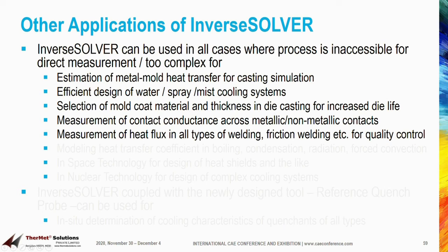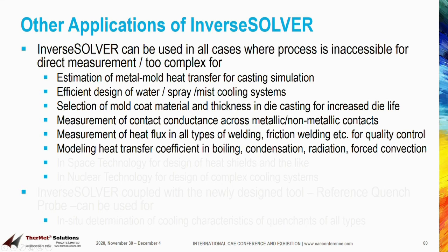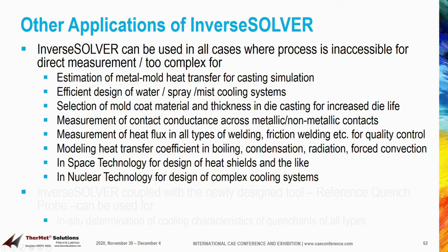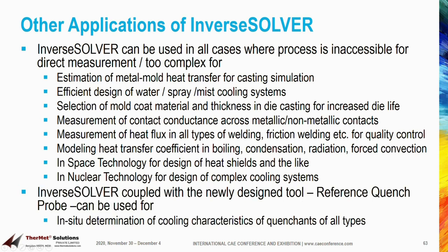for quality control, modeling heat transfer coefficient in boiling, condensation, radiation, forced convection, in space technology for design of heat shields and the like, in nuclear technology for design of complex cooling systems. Inverse solver coupled with the newly designed tool reference quench probe can be used for in situ determination of cooling characteristics of quenchants of all types.